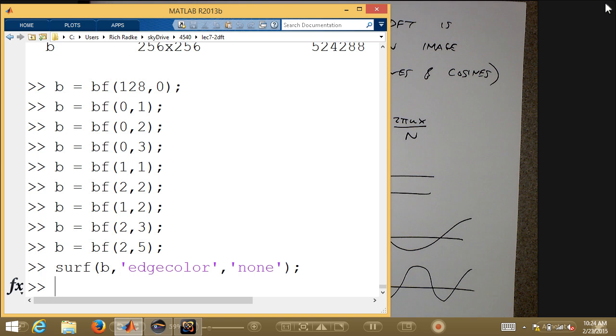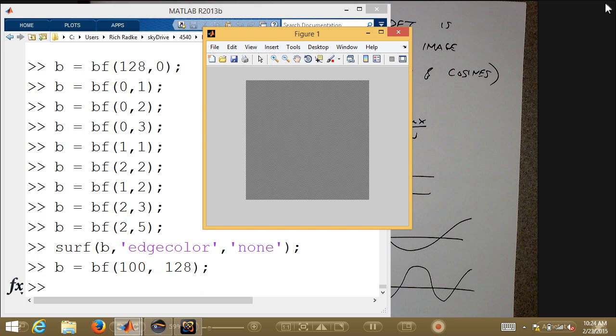Just like in one dimension, let me pause and ask for a second: any questions about the way these basis functions look? In some sense, I think it's easier to visualize this stuff for image processing than for signal processing, because you can really get an intuitive sense of the things that are adding up to make your image, okay? And as a preview of the next lecture, high frequency basis functions start to look basically just like noise. I mean, it's structured, but it's still noisy, right?